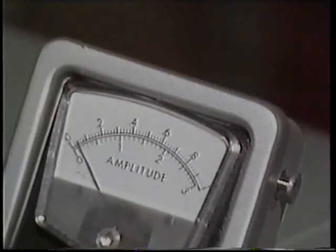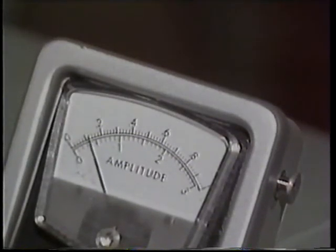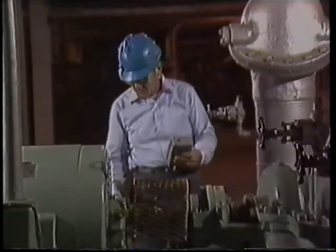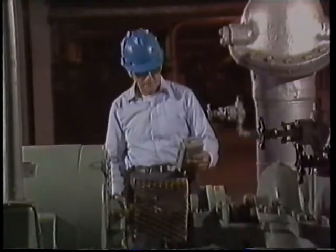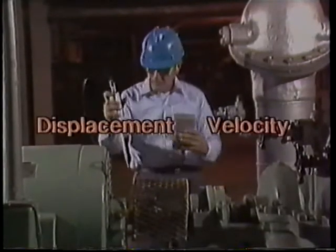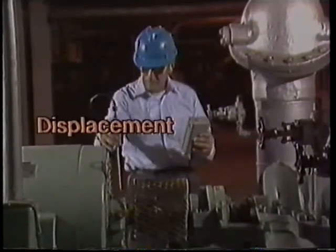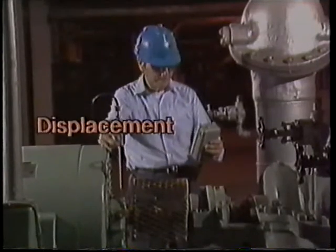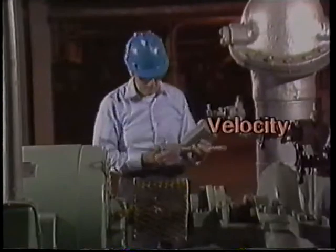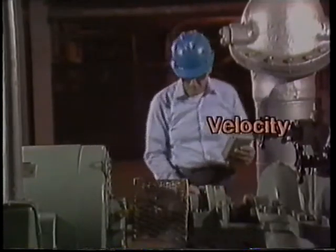The amount of vibration is called the amplitude. Vibration amplitude is a measure of the severity of vibration. The greater the amplitude, the more severe the vibration. Two commonly used measures of vibration amplitude are displacement and velocity. Displacement refers to how far the part moves from its rest position at the center of rotation. Velocity refers to the speed of vibration.